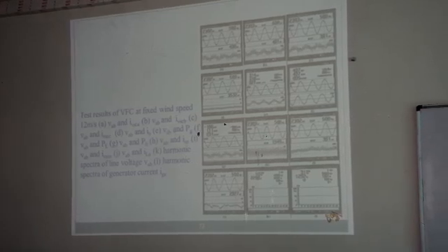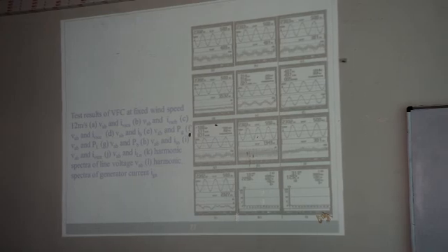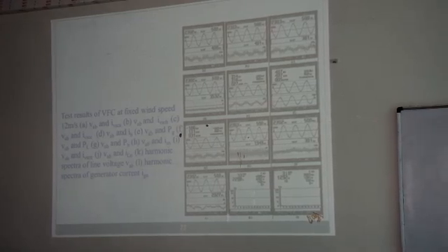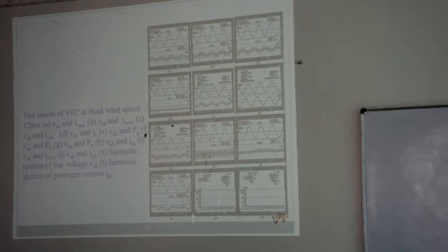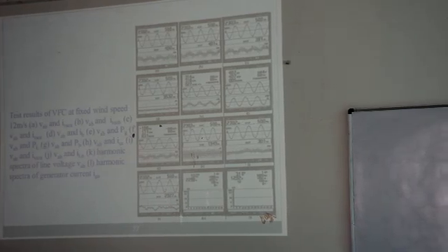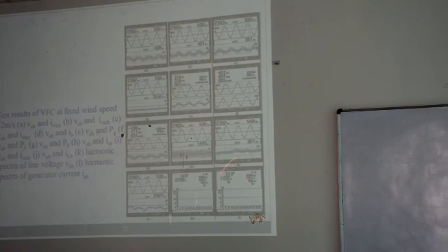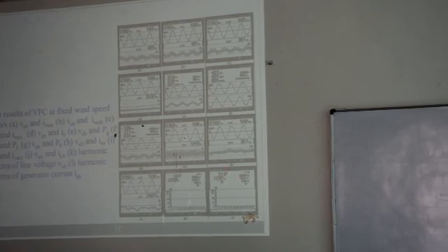Then ultimately we have to take care about the power quality at the load side. So the power quality of your local grid voltage is very good, 1%, and load current THD is also good, 3.1%, because it's a linear load, not a non-linear load.